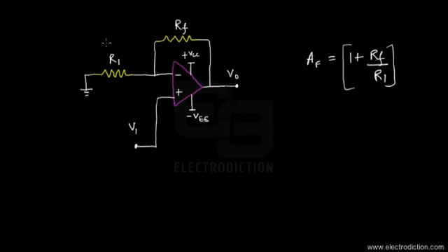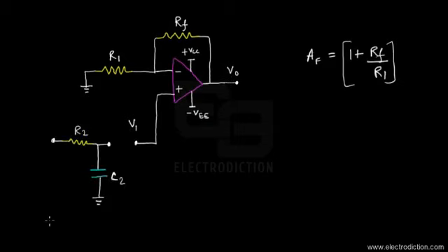Now, as I said, we need an amplifier and also a passive filter, and there's our passive filter circuit. So what we now need to do is join them. Join the passive filter's output terminal to the non-inverting amplifier's positive input terminal. Let's just join it. There you go. So this particular circuit becomes our active low-pass filter, using an op-amp as the amplifying device.